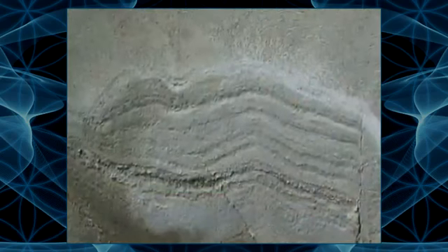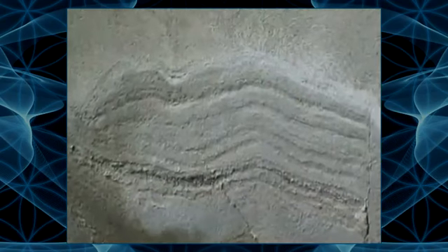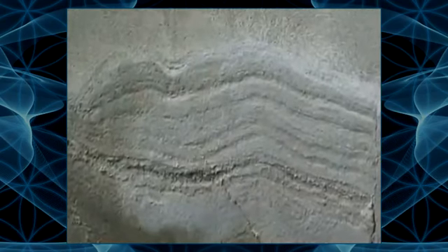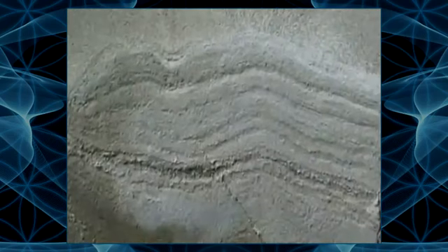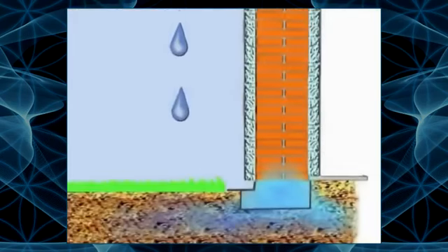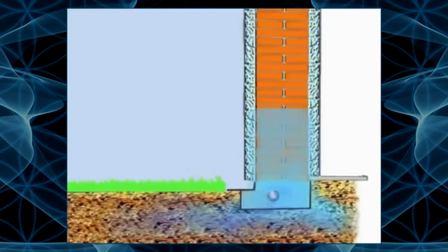It may be manifested as annual rings caused by different degrees of salt efflorescence. Moisture penetrates the ground due to precipitation, dew or groundwater. It then enters the foundation of masonry, where it rises and evaporates, mainly in higher portions of the wall. The greater the quantity of moisture, the larger is the amount of evaporation at the evaporation zone.